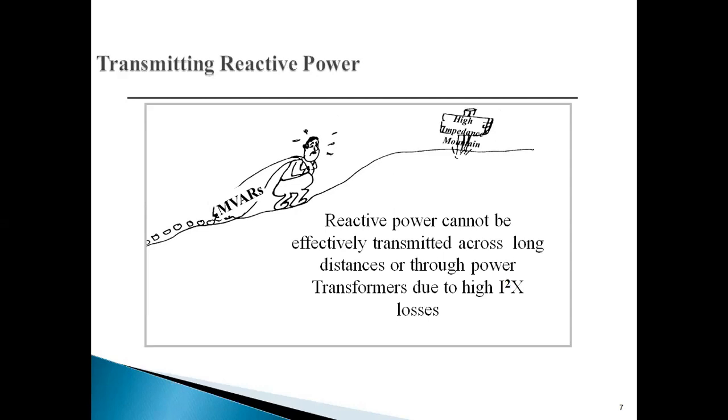For example, if the load is varying in a gradual manner, slowly and steadily, in that case the nature of the disturbance is slow, therefore we call it a small perturbation, so we call it small disturbance voltage stability. Suppose the disturbance is in terms of an outage, when I say outage, I mean out of service, maybe a generator outage or line outage, so a transmission line may be out of service or a generator may be out of service. In that case, what will happen? We call it a major outage, so a major disturbance or large disturbance. That's why we call it large disturbance voltage stability.